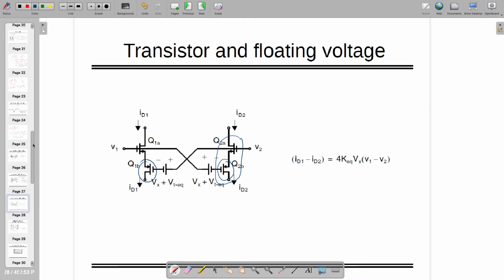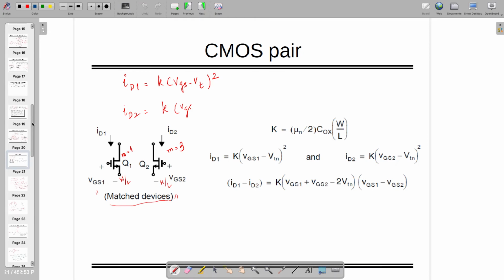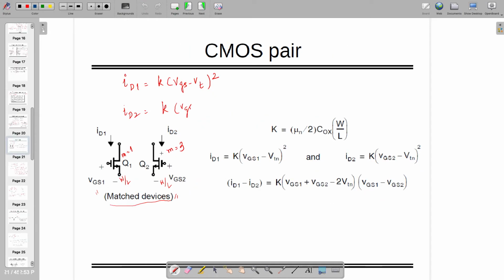If you look at the analysis where we started, we have learned two kinds of topology, where one topology says that two transistors are in cascode, one NMOS, one PMOS, and one topology where two transistors are available somewhere else, not shorted. So for such things, ID1 minus ID2 are known to us, or they are connected with these equations.